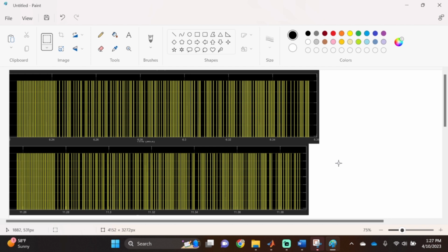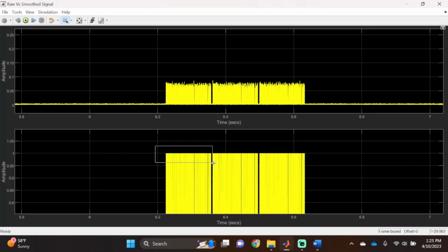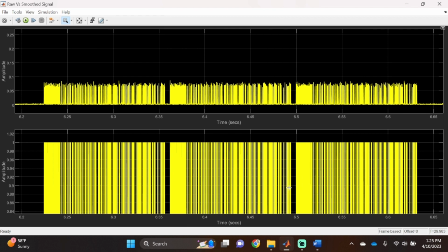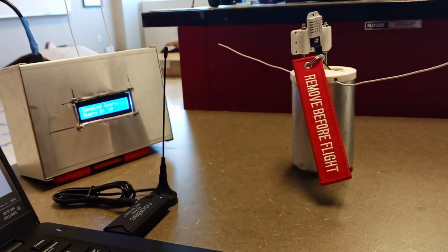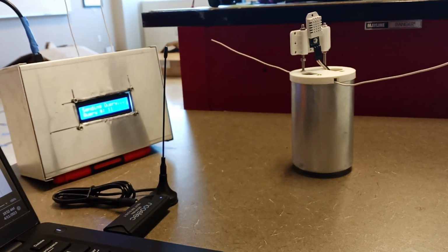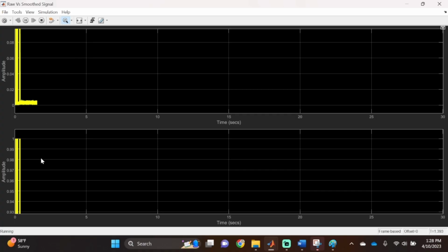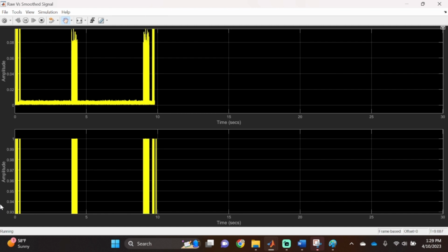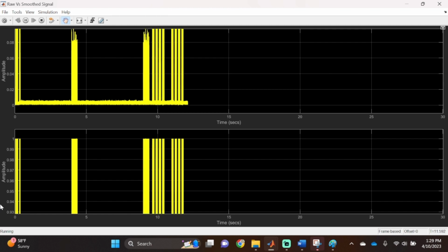Now keep the shape of this train in the back of your head as we initiate the first CanSat in the network by removing this electrical interlock pin. And if we run the Simulink simulation again, you will notice something different shows up. We can still hear the query from the base station radio, but now you will notice that every other query is followed by a new signal train. This new signal train is the reply from our CanSat, and it consists of 4 sections that have a greater spacing between them than the query message.